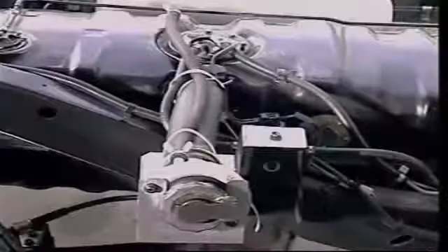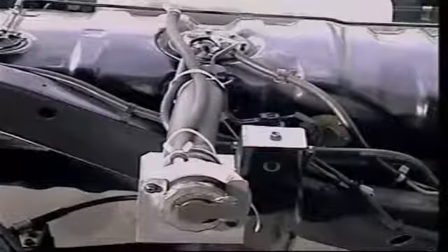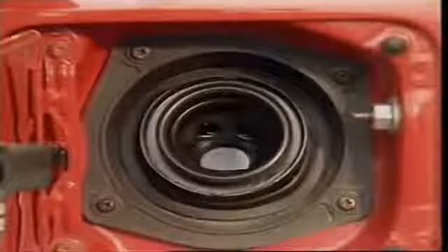The fuel filler is where fuel enters the system. The filler neck is a pipe that extends above the fuel tank. On unleaded petrol vehicles with catalytic converters, the filler neck is designed to prevent leaded fuel being added. Its diameter is smaller than those on leaded vehicles, and a trapdoor inside the filler can only be opened by the nozzle of the unleaded petrol spout.